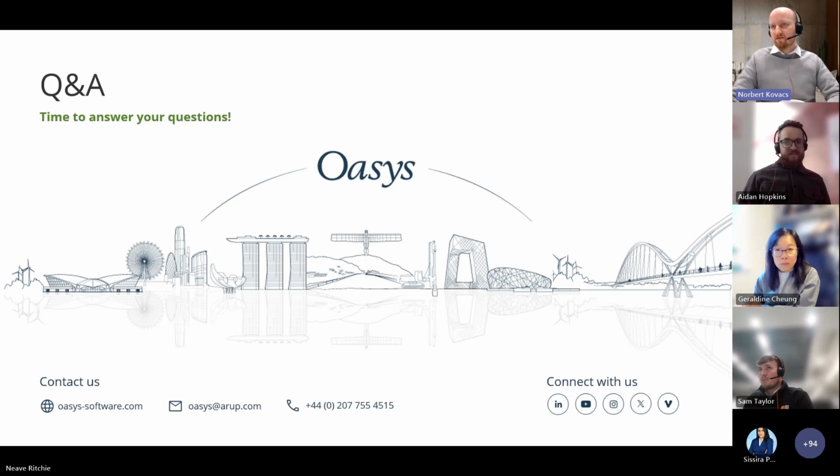And there's actually an addition to this. In particular, asking about ground movement contours with the phase 1 assessment in mind, where you might use the 1 millimeter ground movement contour to define the utilities to include in your phase 2 assessment. In that case, you would need to be sure that the contour used picks up the worst case stage for each utility.